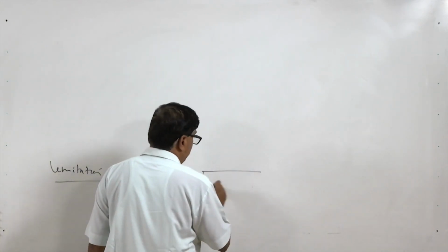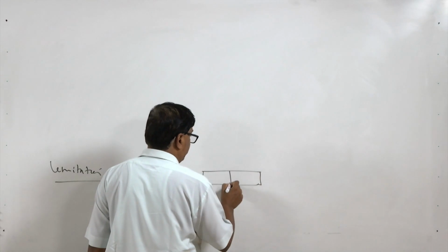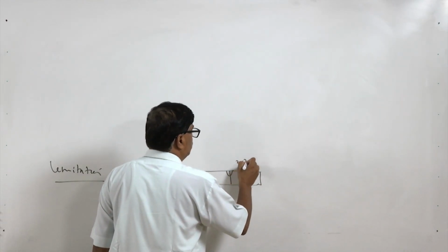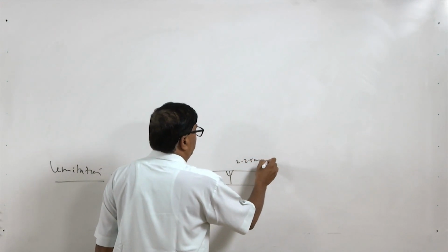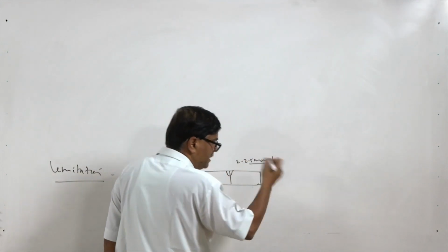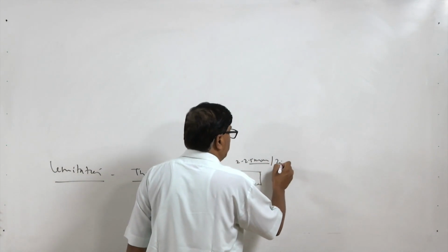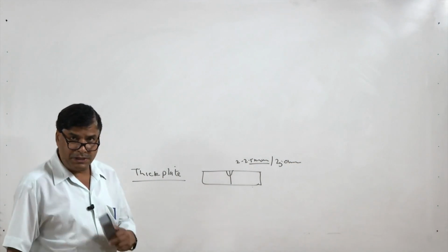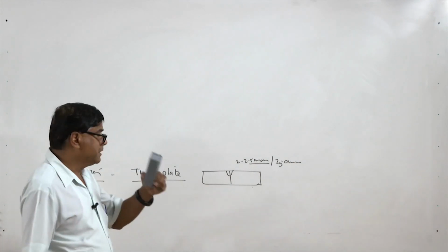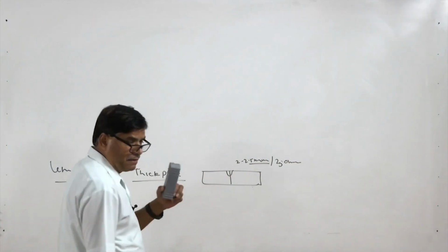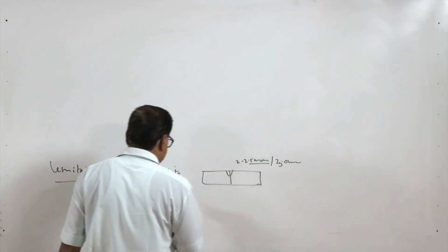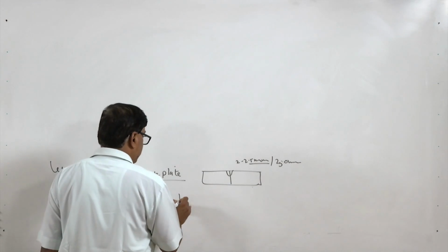One is that the normal GTAW process offers a maximum penetration of around 2 to 2.5 mm, or in very severe, very high heat conditions, maybe 3 mm in a single pass. So, GTAW in a single pass is not tried with the thicker plates, unless some modifications in the process are made. So, the limited penetration is one limitation